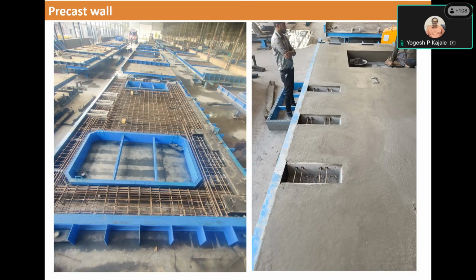In addition to that, wherever we find that there is a possibility of amalgamation of two adjoining flats or amalgamation of two adjoining toilets to convert into a bigger toilet, there we intentionally introduce one partition wall which is constructed with normal AAC block, so that afterwards one can change those particular things.